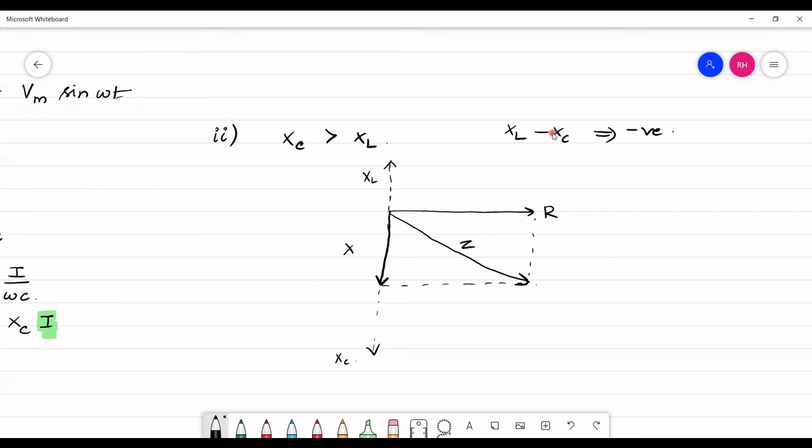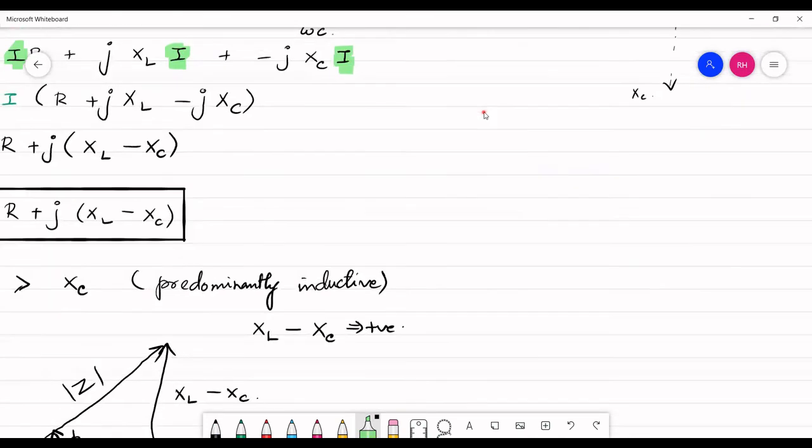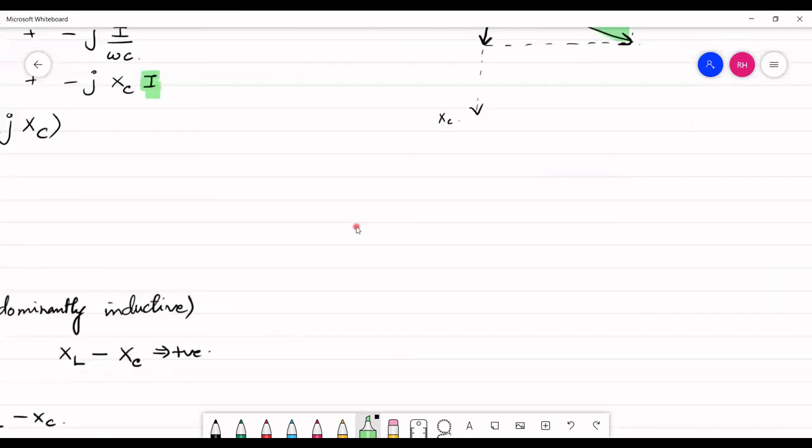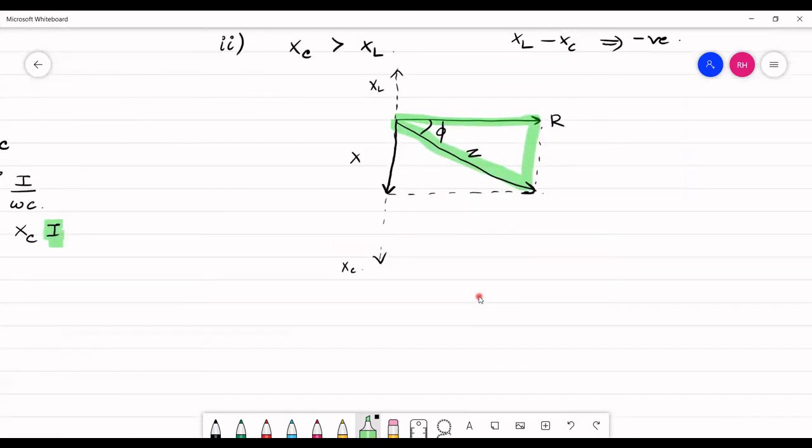So we could also draw something similar to a phasor diagram, and let us say that here we have a triangle and this is the impedance triangle. And now, as we have seen here, after drawing the impedance triangle, let us draw the phasor diagram also. So we have current as our reference. Current acts as the reference. And current, when multiplied with the factor R, we have the voltage drop VR.